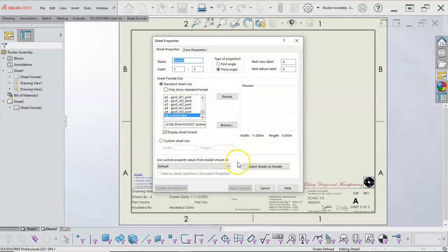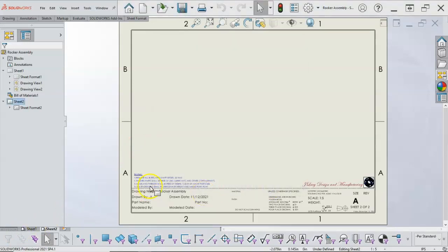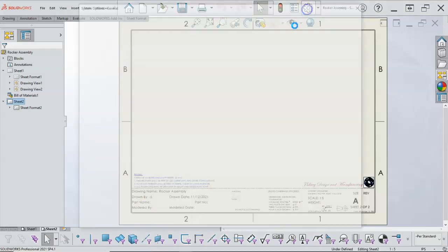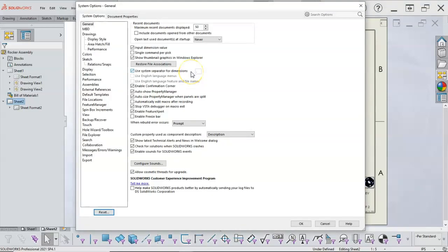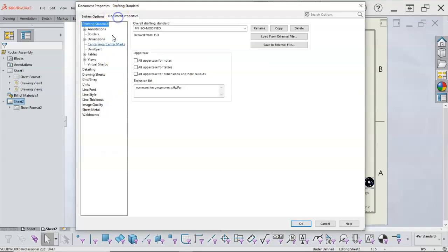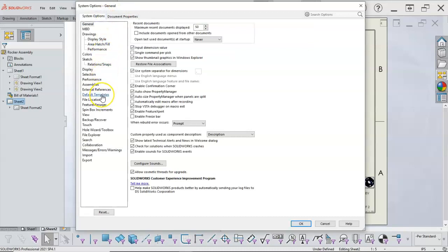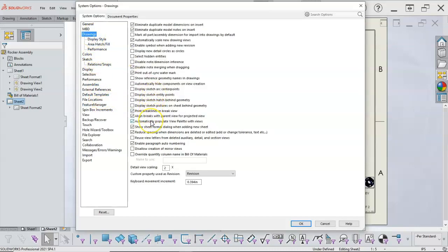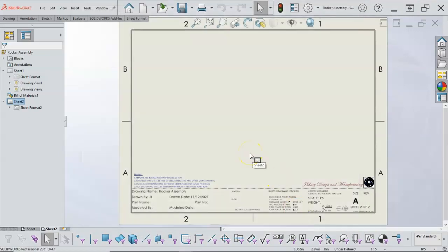Okay, we have the properties. So within our options, we have the ability, and that was set. Let's say the system options were probably set with the document template. So I'll see this again, and if it becomes something that I want to use, then okay. If not, then I will have to save this back too. So show sheet format dialog when adding new sheets. If we hit the checkbox, uncheck it, it should just use that recurring sheet.